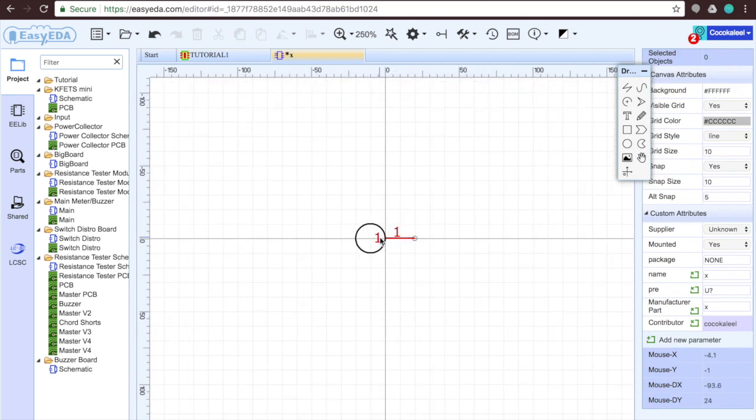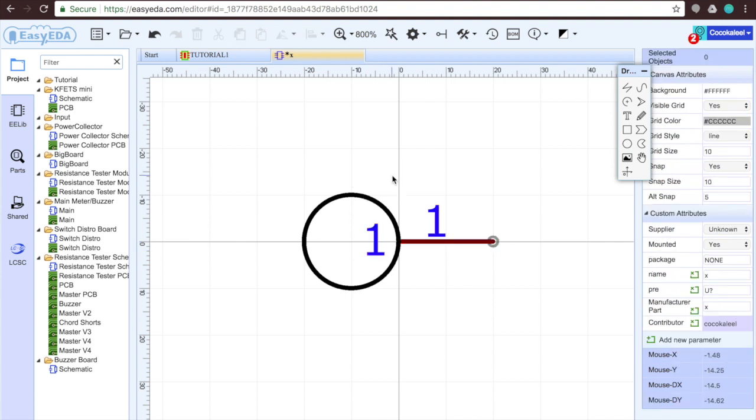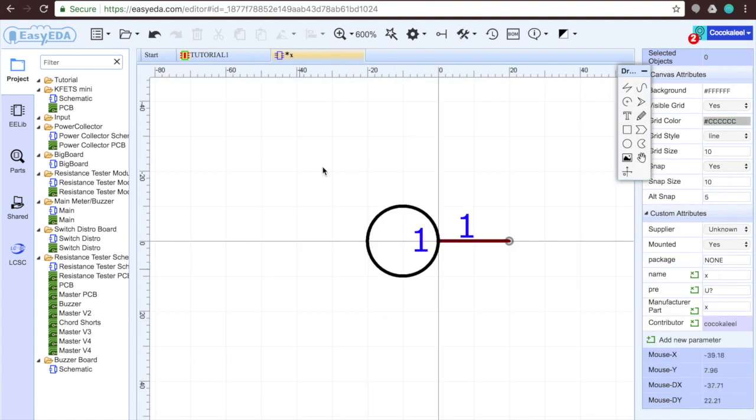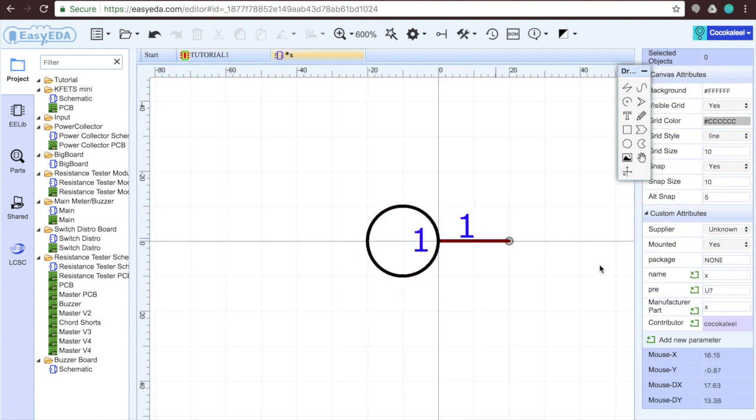This is all I'm going to use for my schematic. It's this one pin, which is the connection site where you're going to connect the wires in the actual schematic, and this is just the graphics that I want for the rest of my schematic. So this is going to be my entire schematic. Of course, if your PCB is more complicated, you're going to want this one to be a lot more complicated, with the same number of pins correlating. I have only one pad here, so I only have one connection pin here.